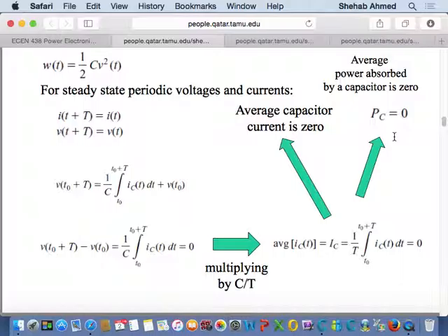You have to charge a capacitor, so current has to flow onto the plates. The plates, the current flow path, all of that has resistance. So there will be a loss, right? And the dielectric that is insulating the two plates has a dielectric strength and dielectric resistance. Fine, it's very high, but there is a resistance there, and then there is leakage current as well, right? So there is an equivalent circuit for a real capacitor, and of course the ideal capacitor that you know about. This is relevant for the ideal capacitor only.